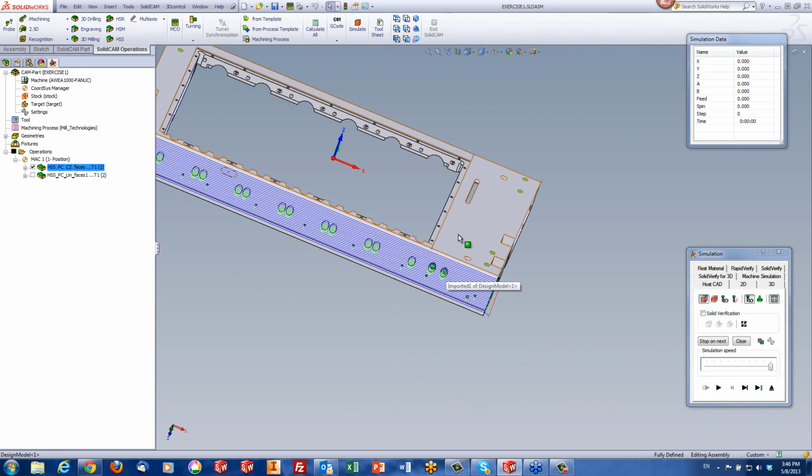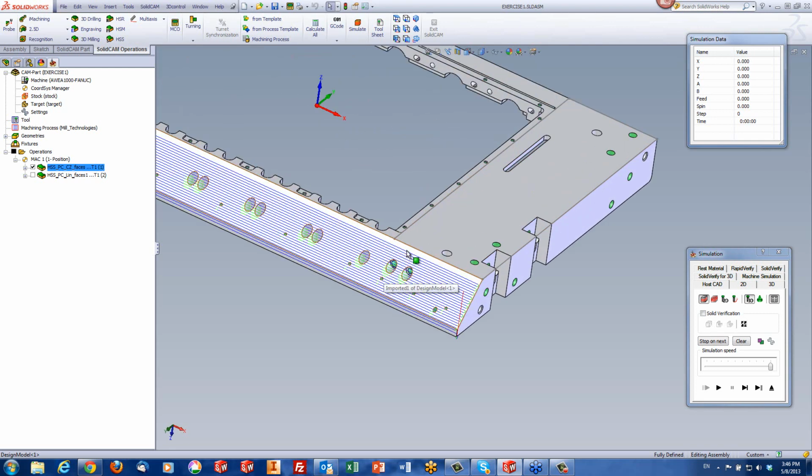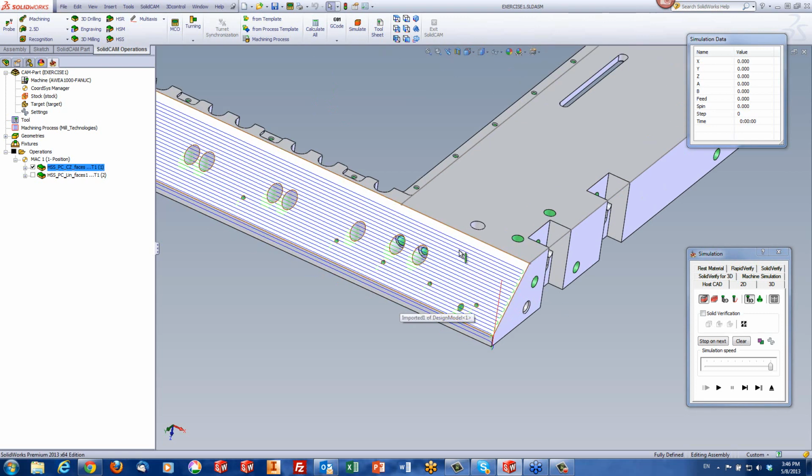Well, the only way to do that is by just taking the surface in SolidWorks itself and extending it in that direction. This option only goes at the ends that it's traveling on. In other words, if it's traveling in this direction towards here, it'll extend in that direction, not over the edges. Okay? If you want to, in this particular case, just go into SolidWorks, create a surface extending it, and then work on that surface instead.